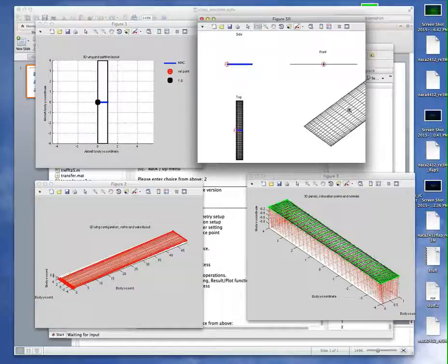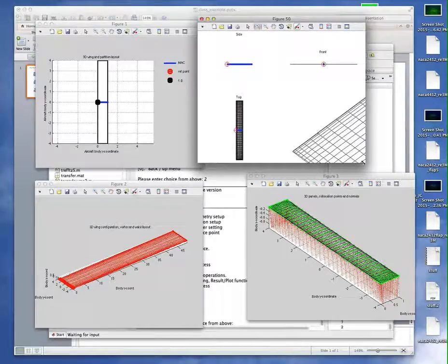Okay, you can see how the mesh is such that you have larger cells or spacing here. As I move towards the tip, they get smaller, smaller, smaller. This is this cosine distribution. And if I go from leading edge to trailing edge, you can also see that they're clustering the panels. A given number of panels are getting clustered closer to the leading edge and the trailing edge than in the midspan. So if you have a given number of panels, that sort of defines the complexity of the problem, the runtime, the compute time. But by clustering them intelligently in regions of high gradient, you get a more accurate solution for a given number of panels.